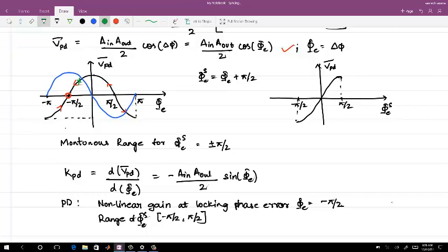No, so the thing is, what's the condition, whether you are in a phase error? The first thing is whether there is a frequency error or not. This is again coming back to the same thing I told you: let's say you start with this point. Good question. Let's say you are here, where the gain of the loop is 0. Which way will it go? It may go slowly to one condition, but that is not the stable condition. So the gain is lesser, but the system is not stable.